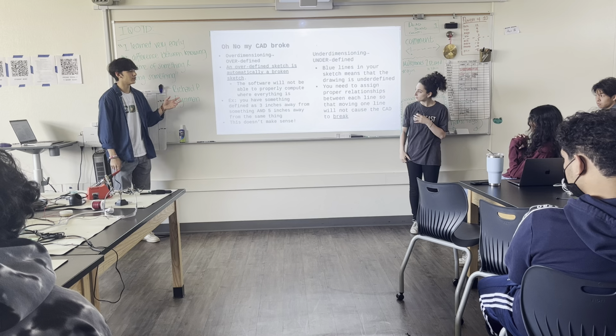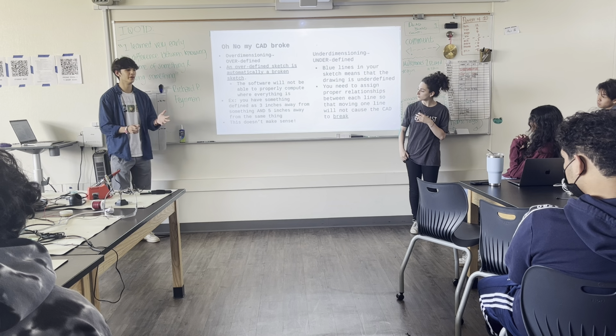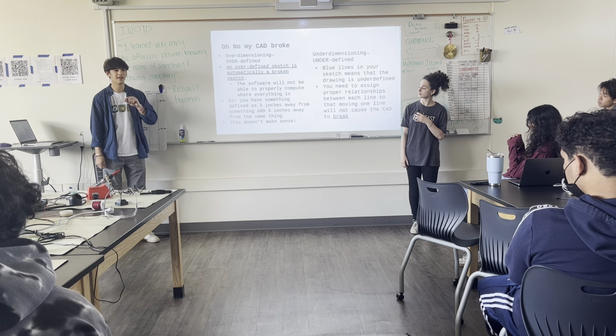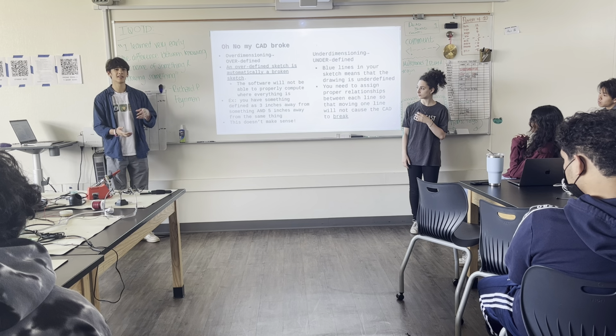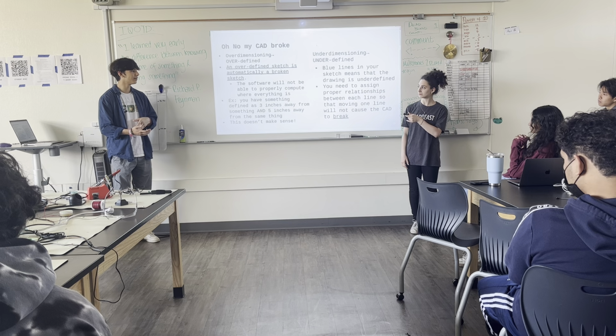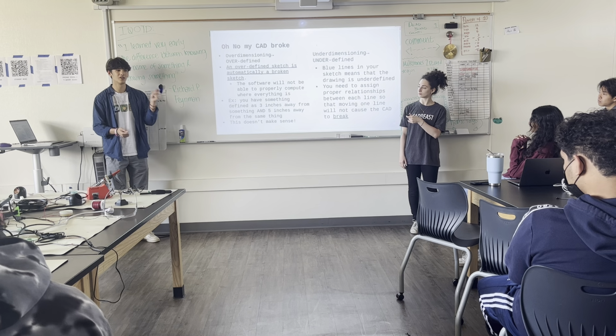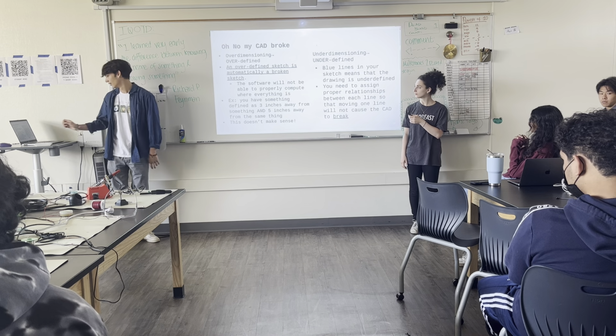Another thing with that is once all of your lines are black and none of them are blue, you'll see that if you try to click on any lines, nothing will move. Everything's set in stone. If you have anything blue, any dots, any vertexes, or any lines that are blue, then you can pull things across, and not everything is set.